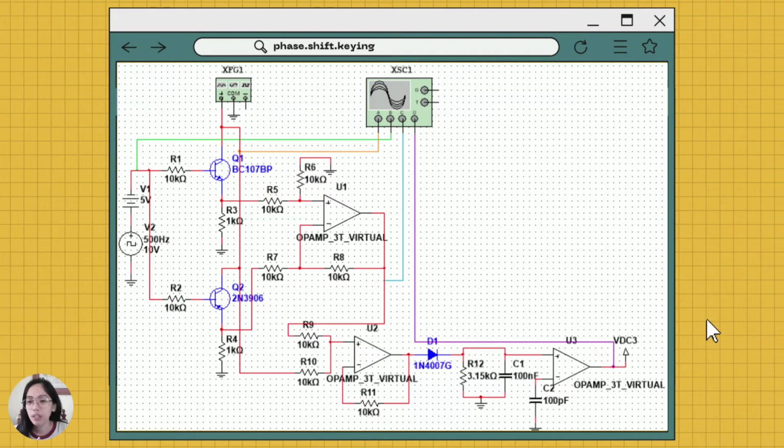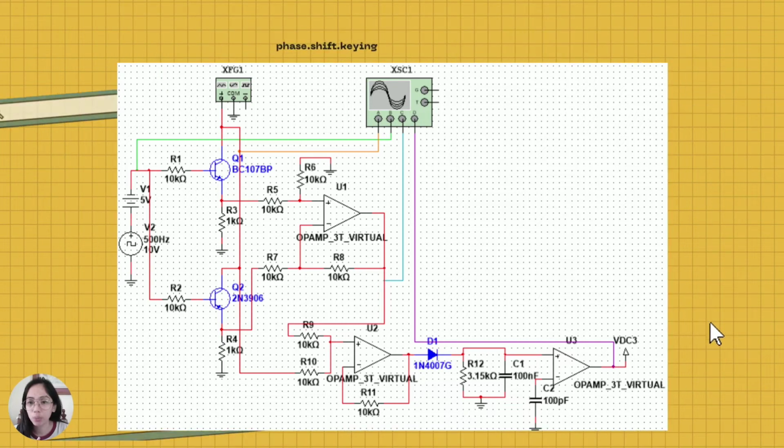Using the 4-channel oscilloscope, connect A between DC power and R1, B on the function generator, C on the output of the op-amp on the modulator, and D on the output of the modulator on the circuit to observe and identify the PSK modulation and demodulation output.